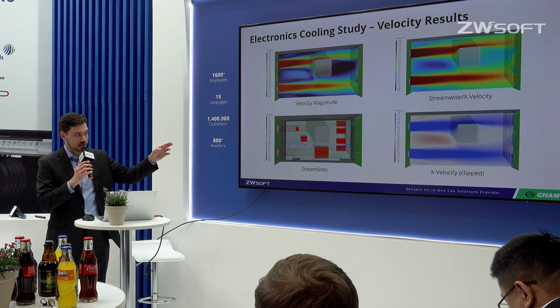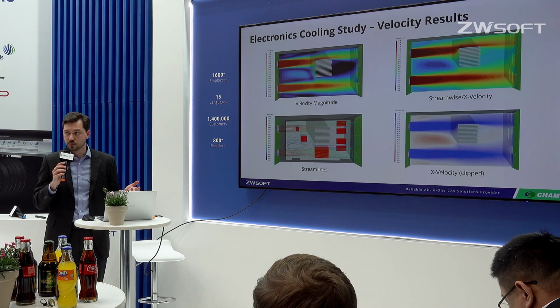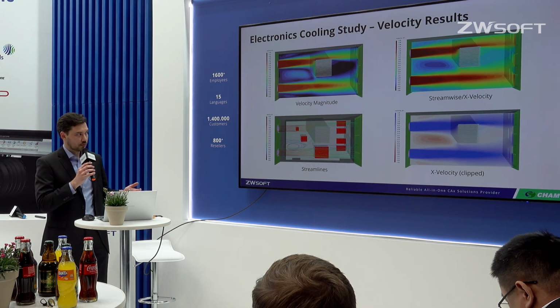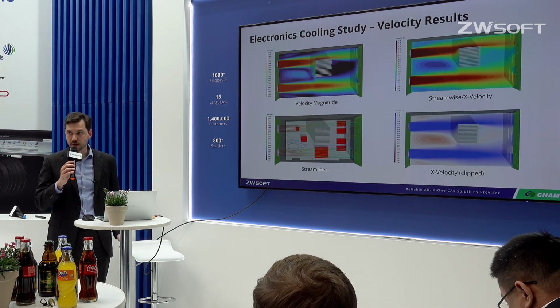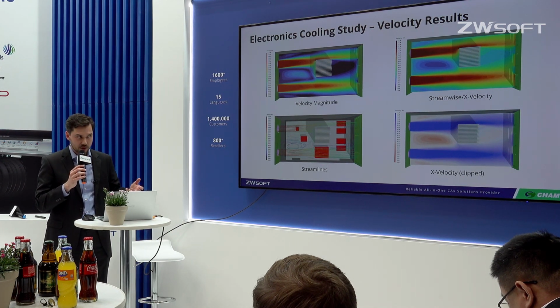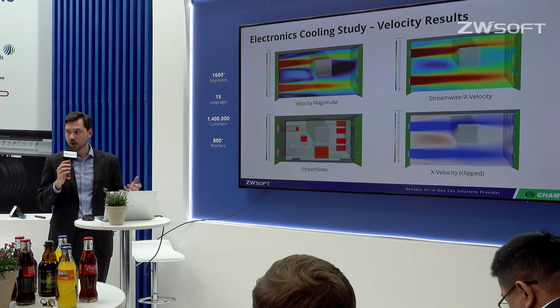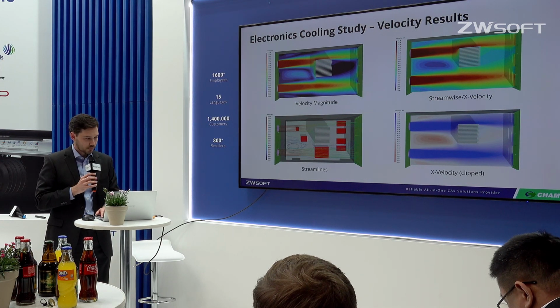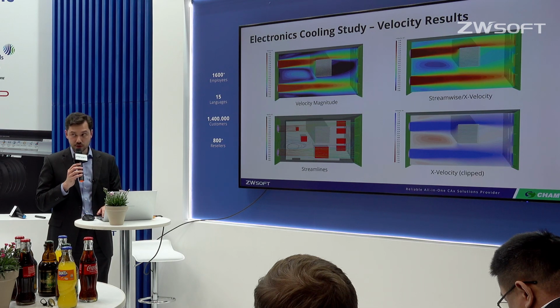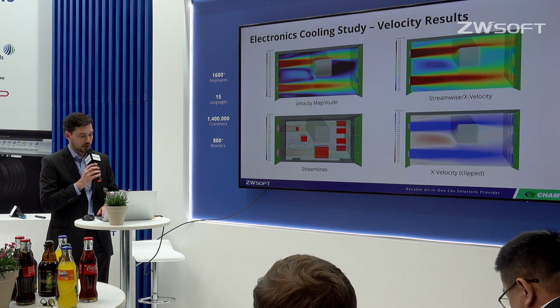And behind the heatsink, we see that there's virtually no flow. So no streamlines actually make their way into there. This is also problematic because it means that there's somewhere where heat can gather up and we might end up with a hotspot, and the chips underneath the hotspot underperforming. So let's take a look at the temperature and see what that tells us about the problem.